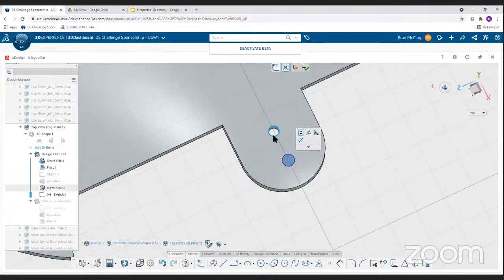Actually, it didn't. Okay, so it didn't actually make it coincident. So if I want to make the two center lines coincident, I'm going to take a point and drop it in the center of this. It allowed me to drop a point in the center of that. So now I'll select the point, select this, I'll let go, and I think horizontal is what we want. Yeah, because if I hit N for normal,